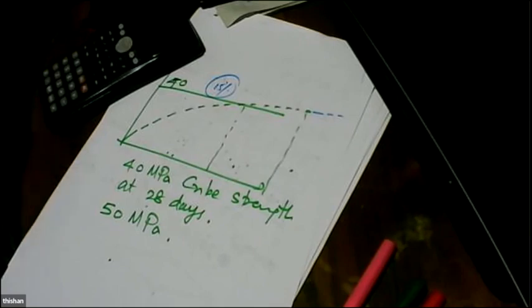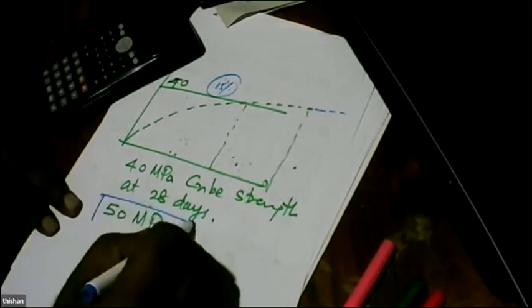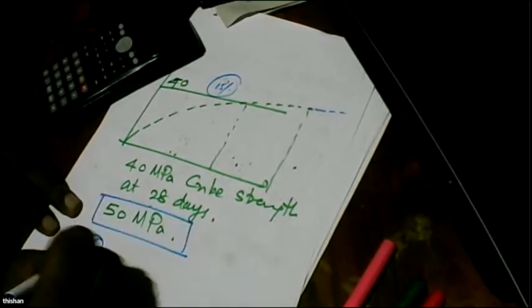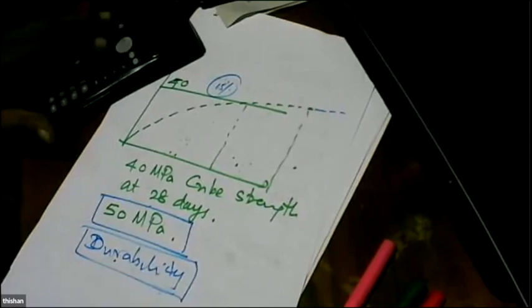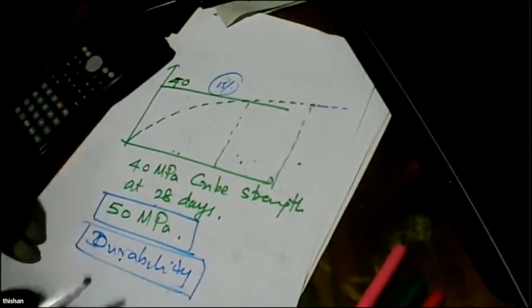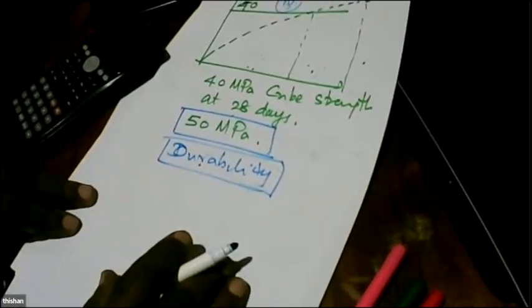And you also know, as far as the reinforcement is concerned, there isn't a huge difference between 40 megapascal and 50 megapascal when it is singly reinforced. But why we go for 50 megapascal is for durability. So by using fly ash with a later age, we can go for durability. Whereas at 28 days, even 40 megapascal is enough. The reason is we know for sure for singly reinforced flange beams, the grade of concrete is not that important.